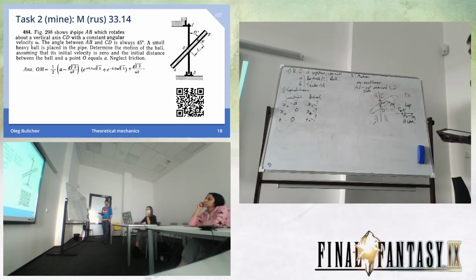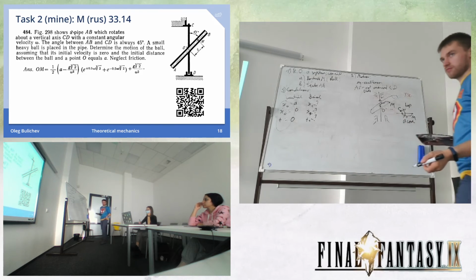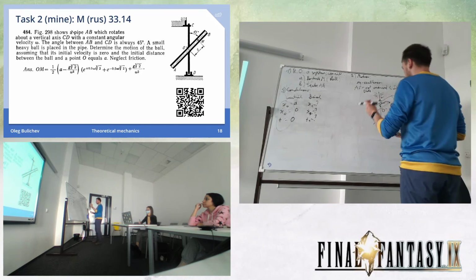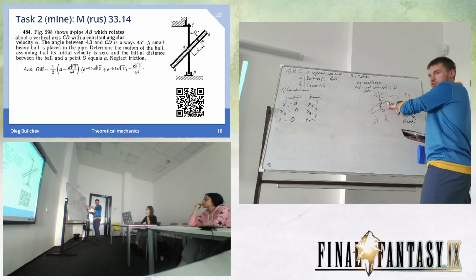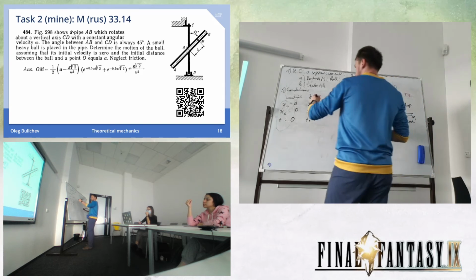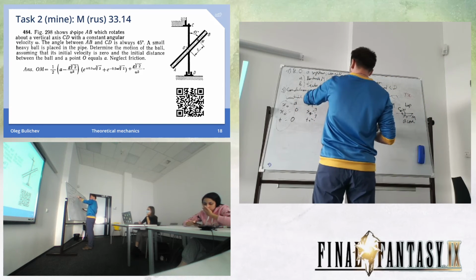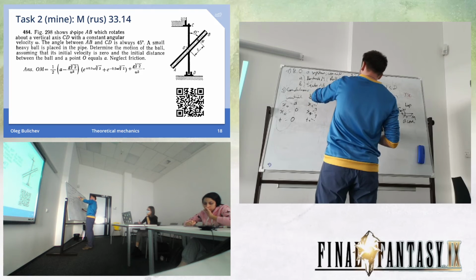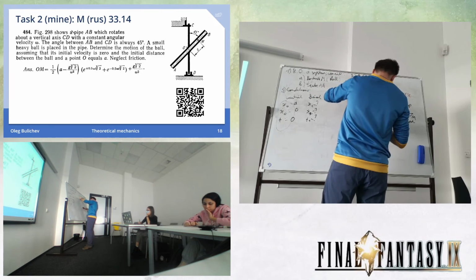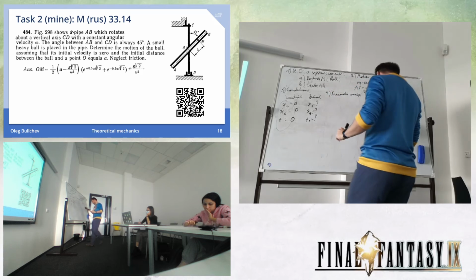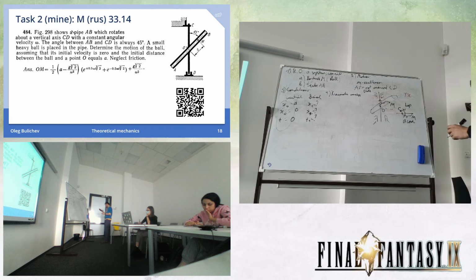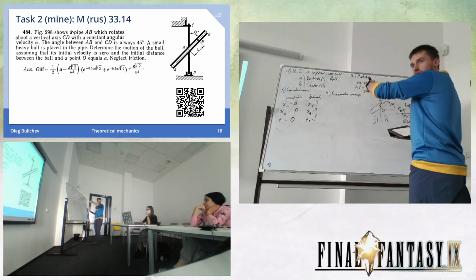Now we have to consider kinematic analysis. What does it mean for us? We are putting in velocities, accelerations, and so on. We need to know the directions of accelerations because of inertial forces. We cannot solve force analysis if we don't know where our forces should be positioned.